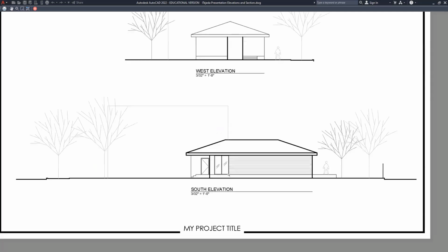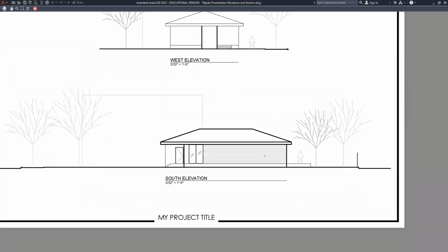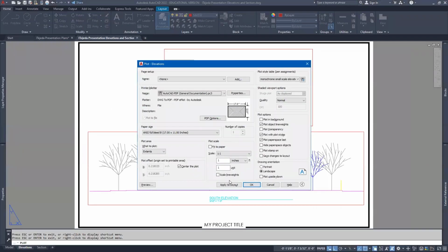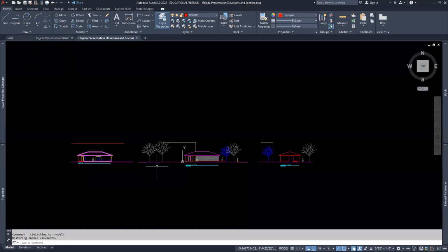because I'm looking at this and I really want my ground to come in just a little heavier. I'm going to use the polyline command. But I like what I see here. I'm going to go ahead, right click, exit. I'm going to apply this to the layout, and then I'm going to cancel. I'm going back to model space, and I brought my elevations here as external references.